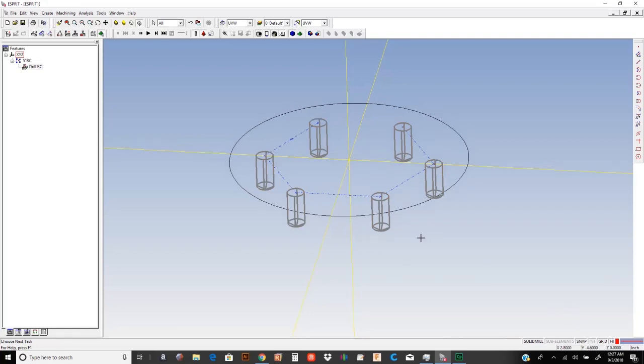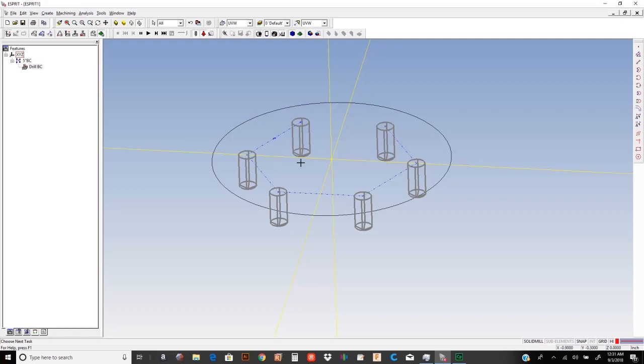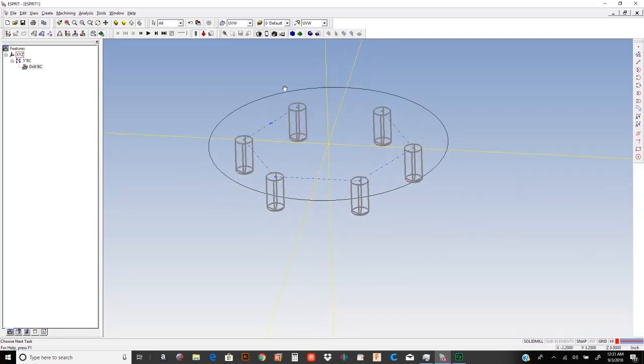Okay, so basically highlight is a selection tool that's very helpful when you have many elements on your screen. You have toolpaths and geometry and different features all stacked up on top of each other. And when you go to select one, if you accidentally select the wrong one, you just right click for no and you left click for yes when it actually highlights the one you want to select. Okay, so I created a toolpath for this simple bolt circle program.